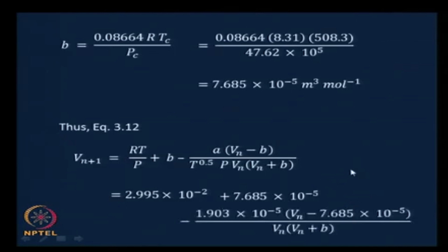And we saw that we had used different formulations of the Redlich-Kwong equation to get estimates of first the vapor volume, by starting with the ideal gas volume as the initial guess, and then a different formulation for the liquid volume, in which we started with the value of B, the volume of molecules, as the initial guess for liquid volumes.